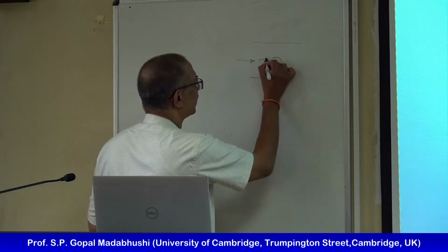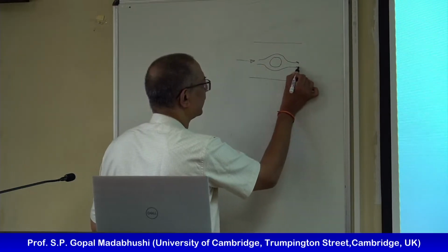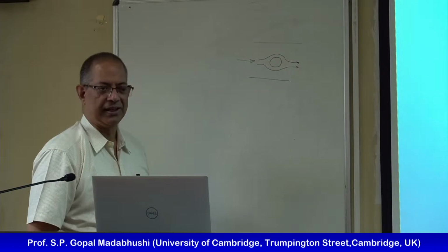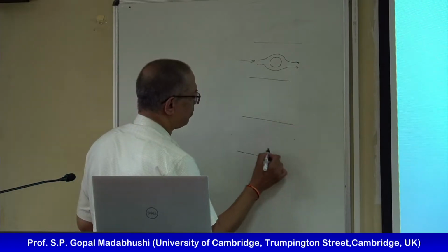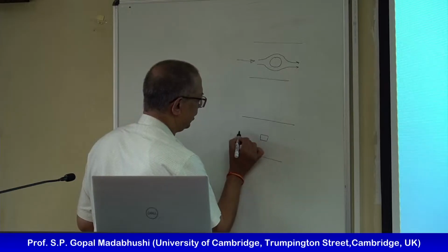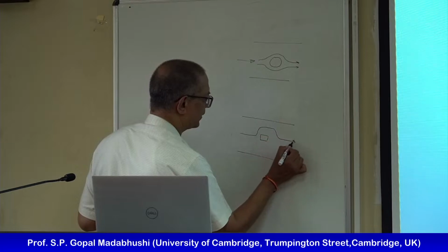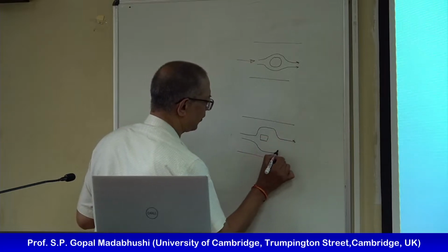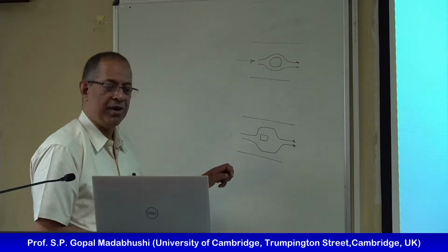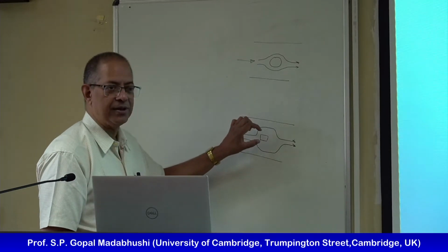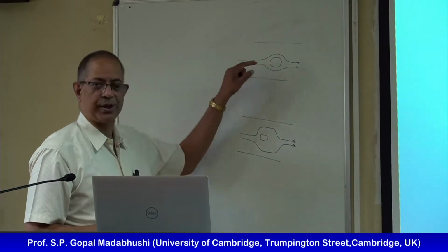What we observed was, say the flow of soil is like that. And for the square pile, what we saw was it was going a lot more like that. So although the bending moment is the same, the zone of influence of a square pile was much wider than the circular pile.